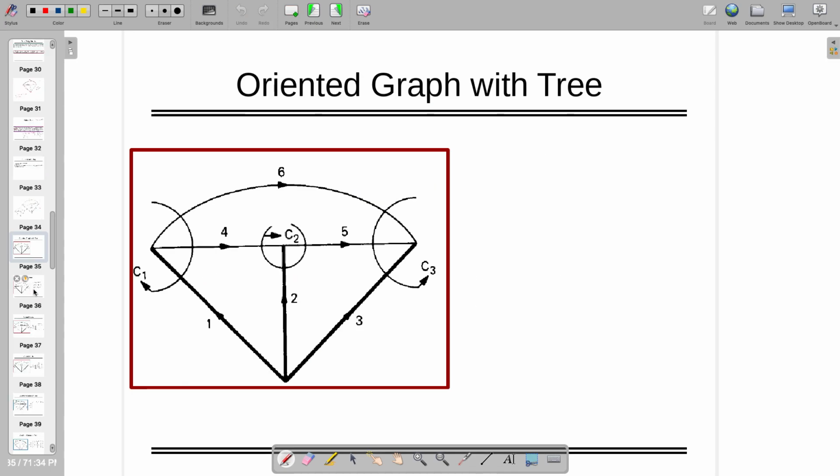Okay. So as I told you, the number of cuts is equal to the number of nodes. So there are 3 nodes available, excluding the 0 voltage node. So you are going to have 3 cuts. When you are making a cut, that particular cut will have one twig and more number of chords. This is the only rule.